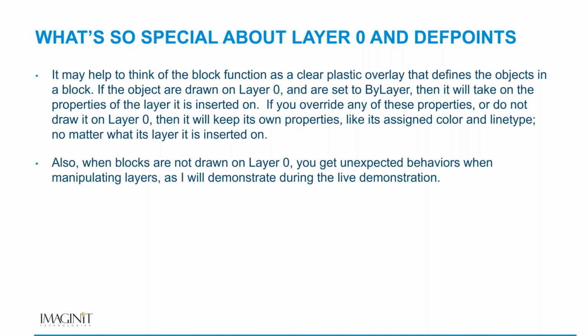If you override any of these properties, or something is not set to ByLayer, or you do not draw that block on Layer 0, then it keeps its own properties, like its assigned color and linetype, no matter what layer it's inserted on.